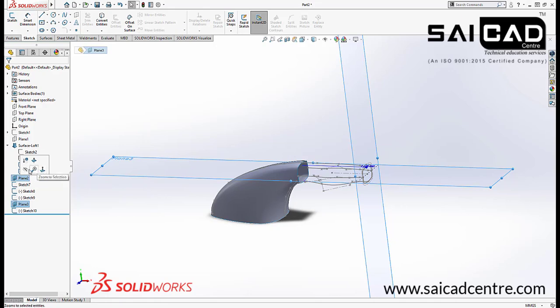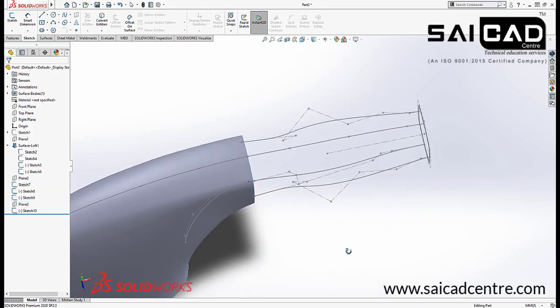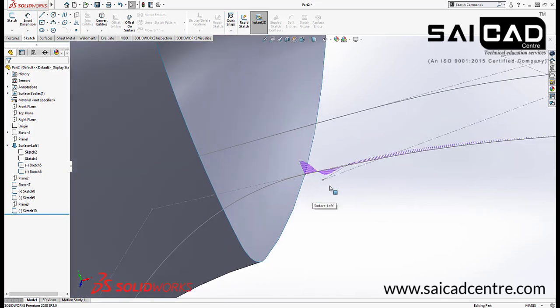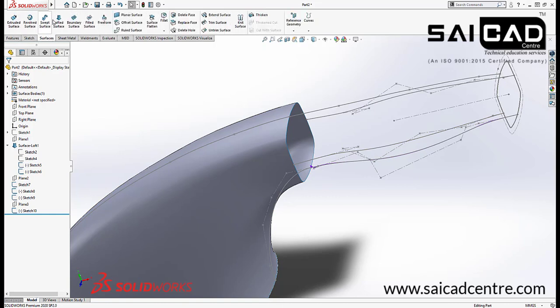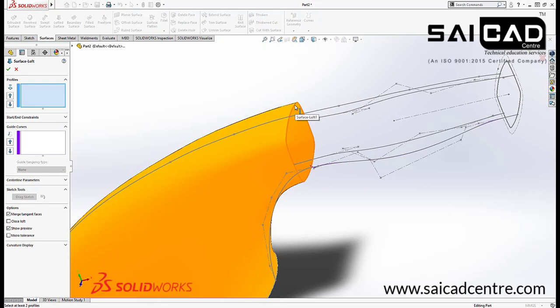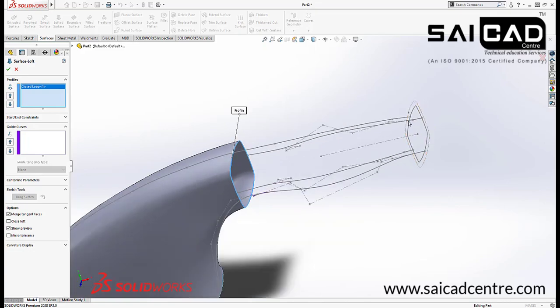planes from here. So we got multiple options here. Okay, I have turned that on in the sketch, so you can just turn that off also. So now go to the surface, go to the loft, and now remember we are going to use this shape from here, so I'm going to use the loft surface from here. So go to the select, and I will just go and select that. Okay, click OK. So you got the closed loop from here, and now go here and select that.